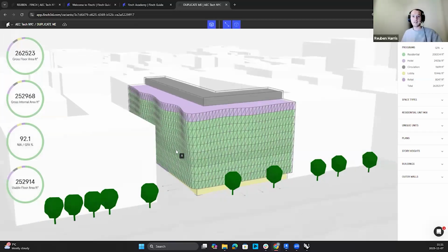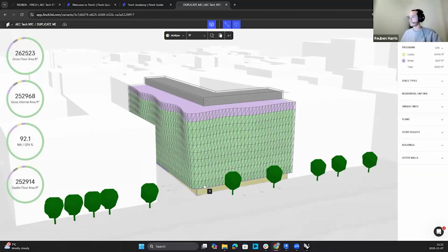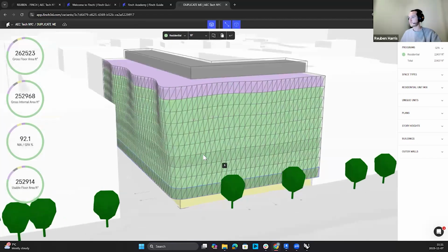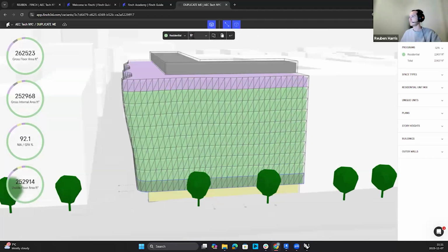Okay, back in the massing studio, what more can we do before we dive in? Well, when you've clicked on the floor, you will have seen that there is another option next to program, and that's our floor height. And here we can update our floor heights. With a complex mesh like this, let's see what happens if I make this ground floor 12 feet instead.